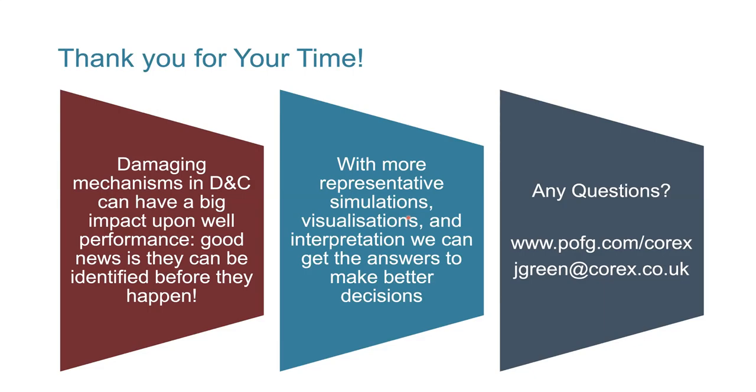Abdulaziz asks, during the drilling process, filtrate is measured in the lab using static fluid loss cells to simulate volumes of filtrate invaded. But do you think, considering the reality, a dynamic fluid loss test can be simulated to reflect the actual process to measure fluid loss, which will show higher magnitude? Excellent question, Abdulaziz, and I 100% agree with you on that as well. I didn't dive deep into, again, it's a separate webinar, how do you do these kind of studies?